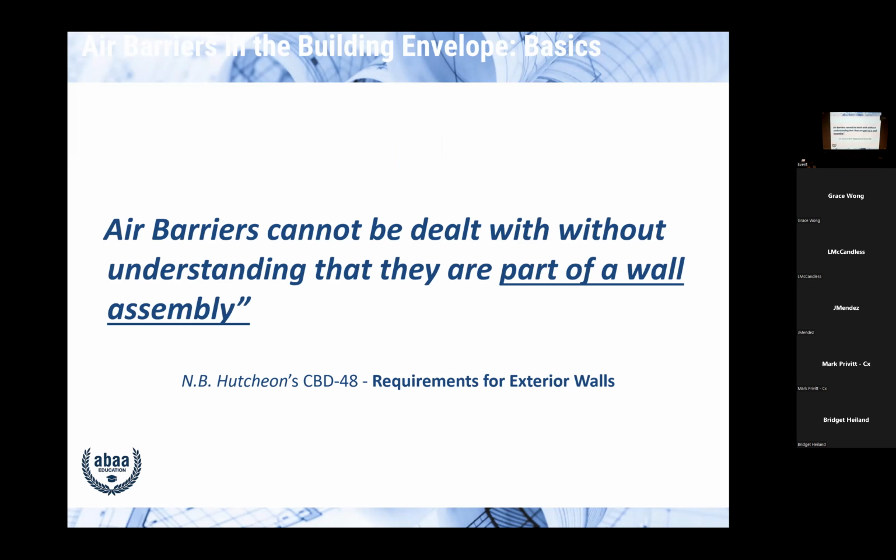It depends. And for you to have air come out of your attic, what do you need to go into your attic? Yeah. Cubic foot of air leaves, cubic foot of air comes in. Where do you think it was sucking that air from? Yeah, the house. So you would see in the middle of December, it's frozen shut. You can't twirl because it's frozen in place.